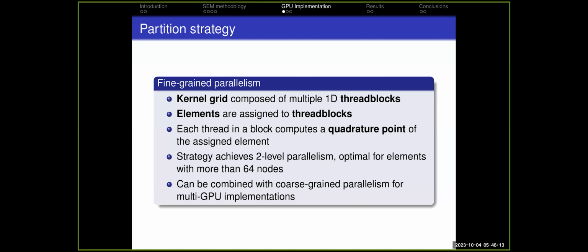And of course, as mentioned before, this strategy is easy to combine with multi-GPU implementations, because once the assembly of the convective and diffusive residuals is carried out for each partition, we just need to ensure proper communications at the halo nodes. This is based on an RK method, explicit RK4 advancement, for example. This requires one communication per substep of the Runge-Kutta, which is actually quite cheap.